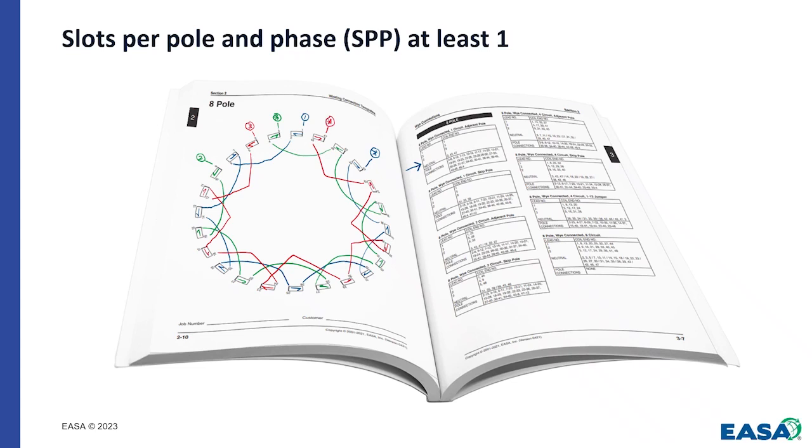So a finished diagram for that 8-pole machine. And when you go around and count these groups, you can count the 8 poles. It's very visually easy to see that for each phase we've got 8 arrows, and those alternate in polarity. And if you look at the 2 phases beside those, they have a different polarity. So you've got that alternating polarity that a conventional winding is going to have. And it's nice. It'll look symmetrical.